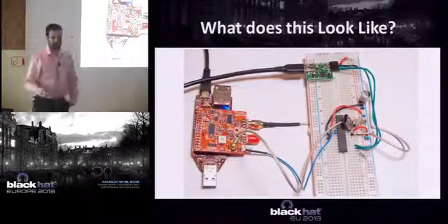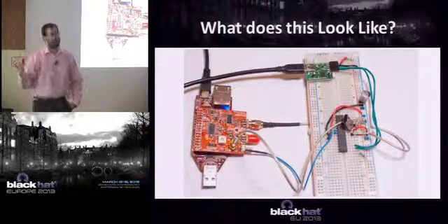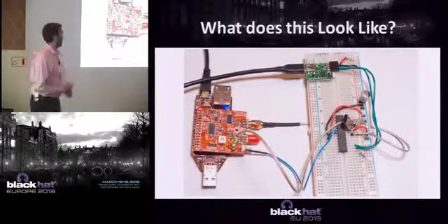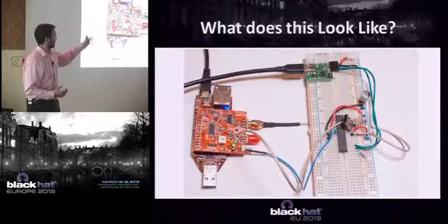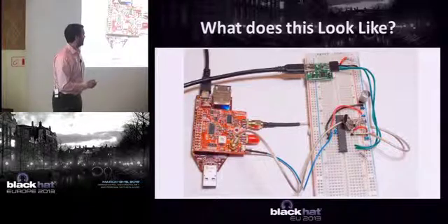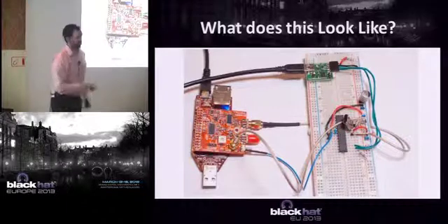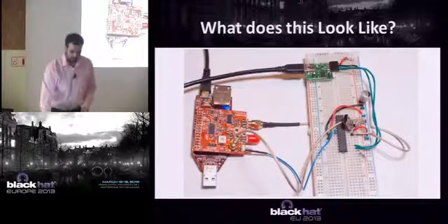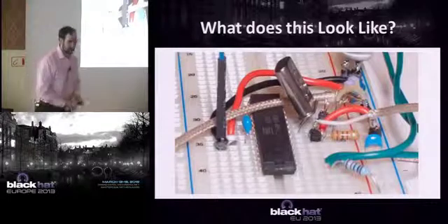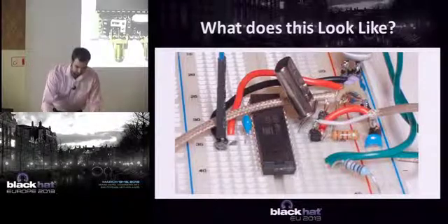So my suggestion, if you are interested in doing this, is to not buy one of those smart cards, because they can be a little trickier to find and expensive, and you need that reader. Instead, just attack an AVR microcontroller like the type used in the Arduino. You can build up something on a breadboard like I have here, and we have a crystal, we have a shunt resistor under there, and I'm measuring the power across the shunt. I have the clock frequency coming out here, and I have a little USB to UART board to send and receive data, and also for power in this case. So, very simple. These might be parts you already have hanging around somewhere in a lab.